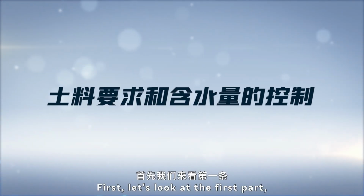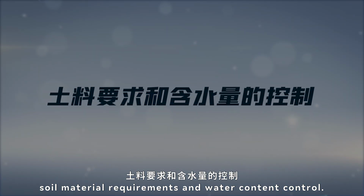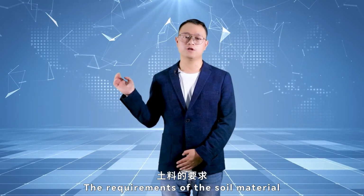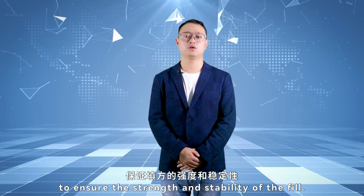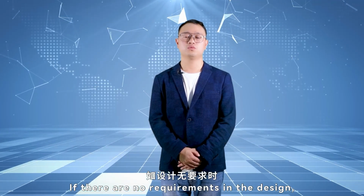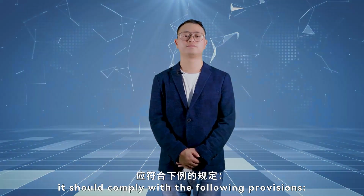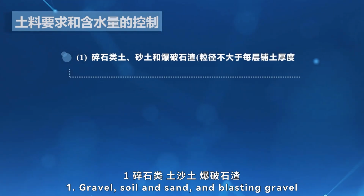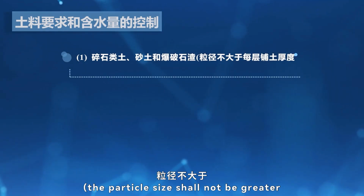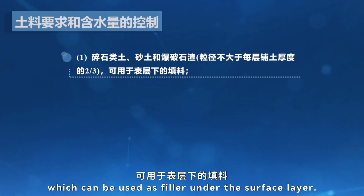First, let's look at the first part, soil material requirements and water content control. The requirements of the soil material should comply with the design requirements to ensure the strength and stability of the field. If there are no requirements in the design, it should comply with the following provisions: 1. Gravel, soil, and sand, and blasting gravel. The particle size shall not be greater than 2/3 of the thickness of the soil laid per layer, which can be used as filler under the surface layer.